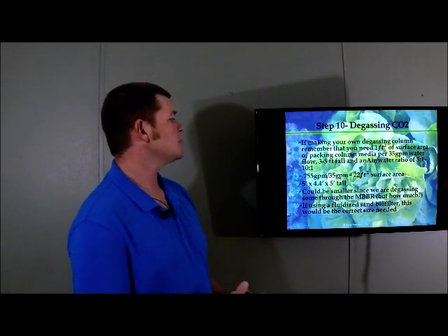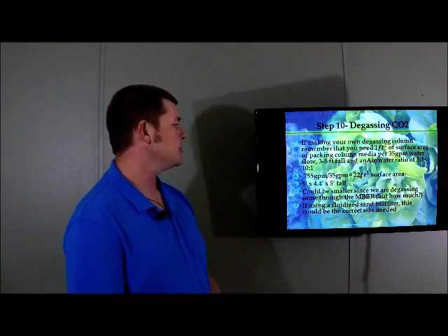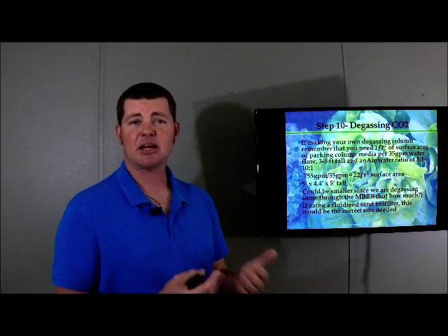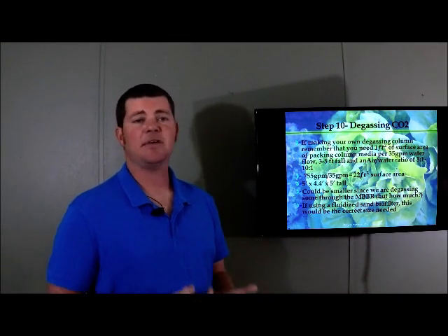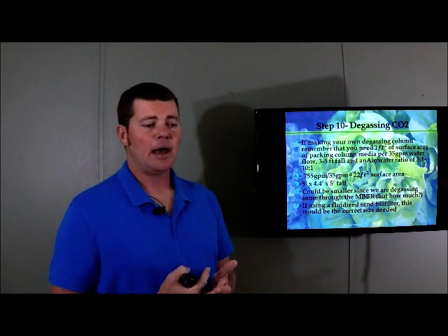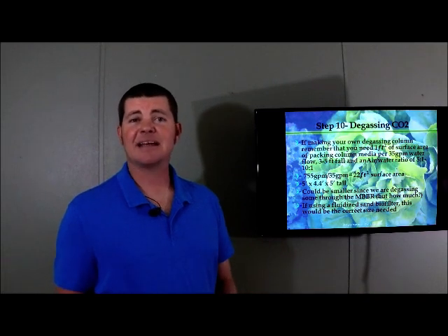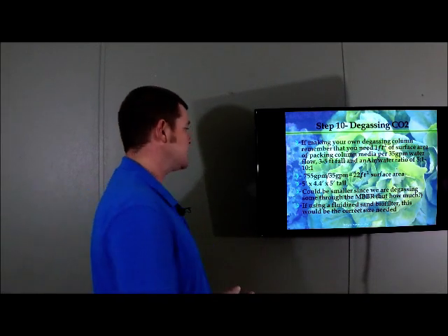Okay? This could be smaller since we are degassing some through the MBBR, but how much are we degassing? We'd have to actually look at some specific CO2 degassing studies from an MBBR maker, and then estimate how much is being degassed through that process.